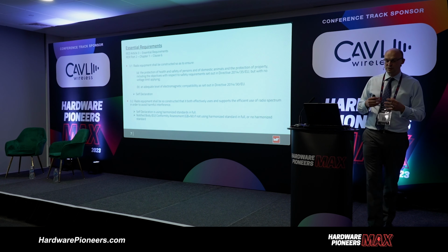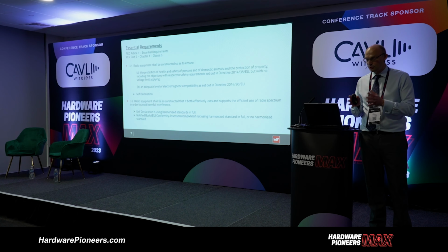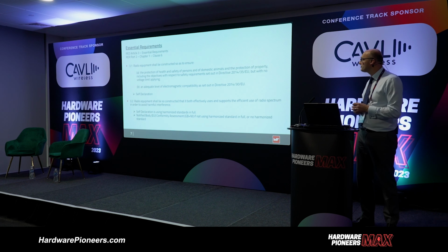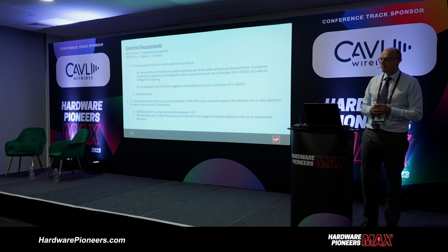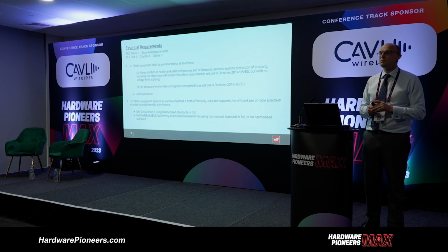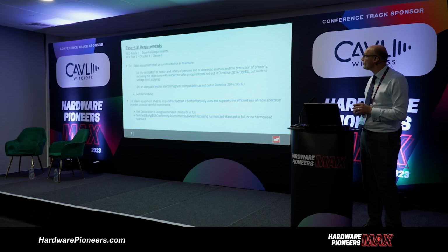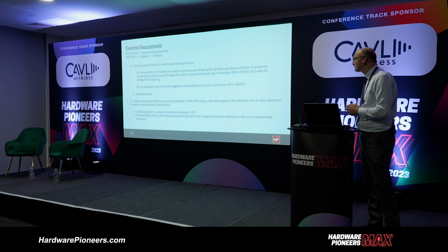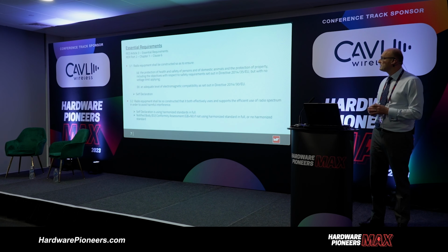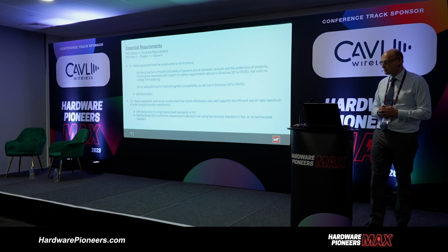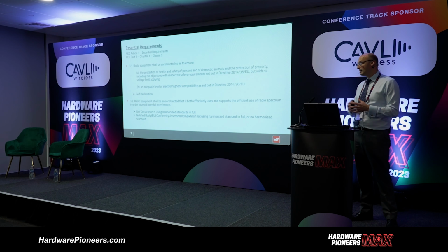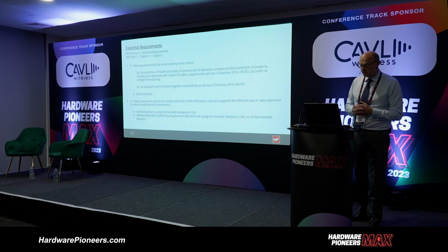Another thing to note when you're implementing a radio module into a radio product is that this particular directive amends the lower voltage limit of the Low Voltage Directive, with no voltage limit applying, so basically from 0 volts DC. So there's a slight difference there. The other thing is then electromagnetic compatibility, making sure that your product does not interfere with intentional RF transmission services.